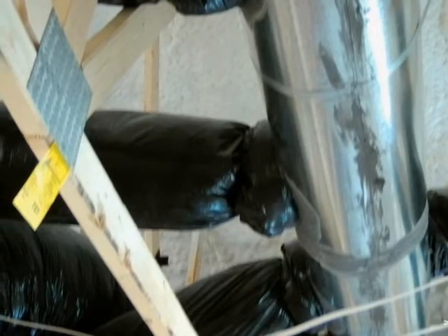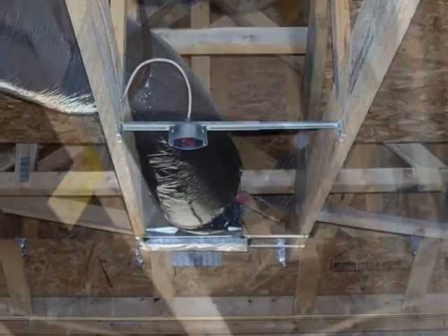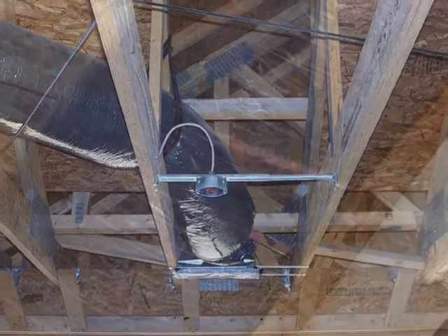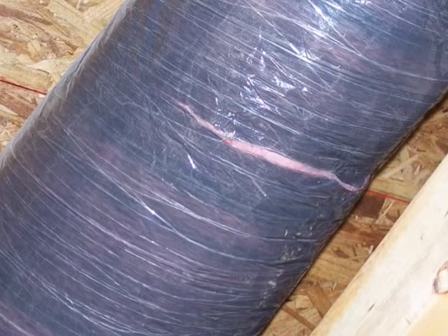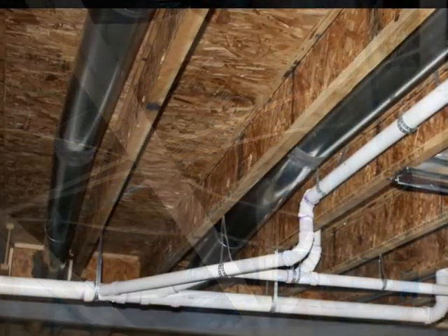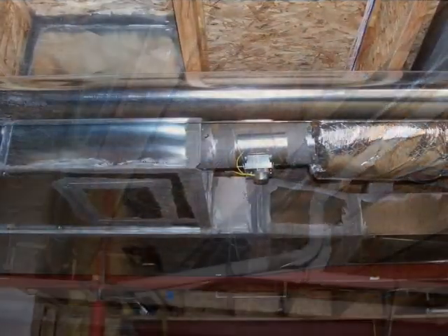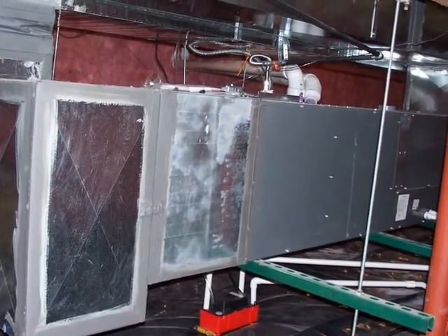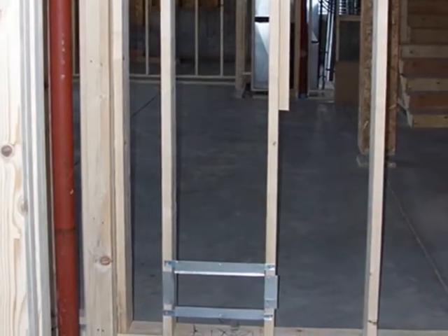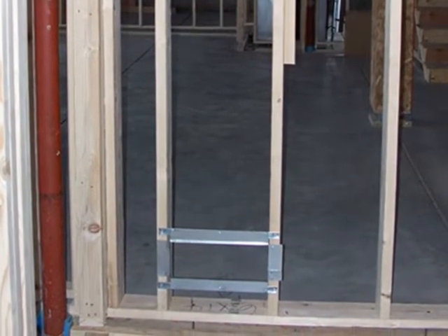What are some of the requirements for the ductwork according to section R403.3.1? If located outside the building's thermal envelope, they're required to be insulated with various R-values. Makes sense? Depending on the size of the duct and its use. We also are requiring that the ducts be sealed, along with air handlers and filter boxes, per section R403.3.2. Building cavities are not permitted to be used for ducts or plenums in any way, shape, or form.